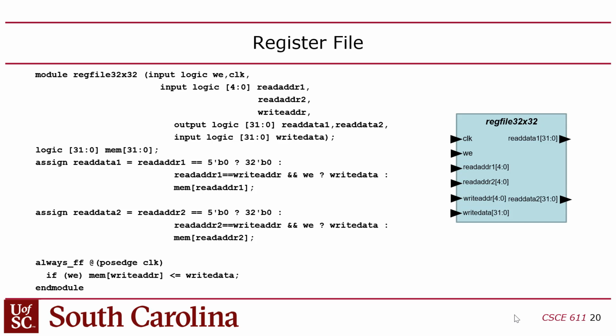Yeah, you could. It would still be synchronous then, technically, just synchronous on 2 different clocks. But yeah, you could do something like that. People have done that. In some architecture textbooks, that's the way they do the bypass: they say that you write on the falling edge and you read on the rising edge. That way they could make it synchronous, but they could still achieve this bypass behavior, so you can read and write at the same time. We could have done it that way too. That's possible. It still wouldn't go in a RAM though, because of the 3 ports.